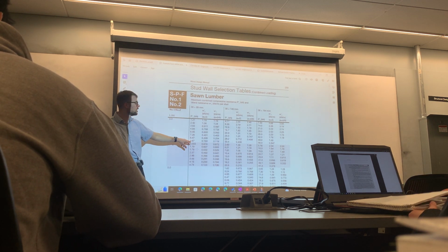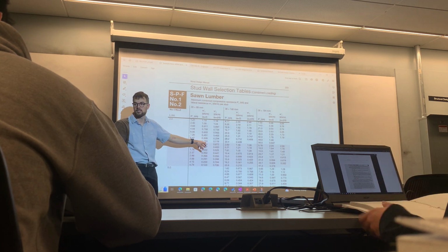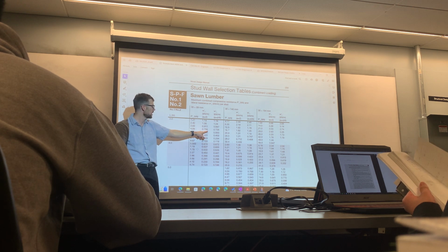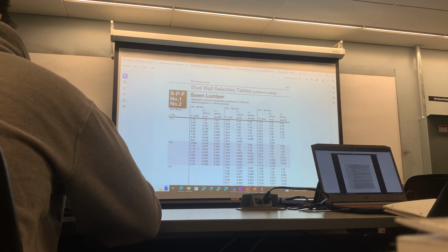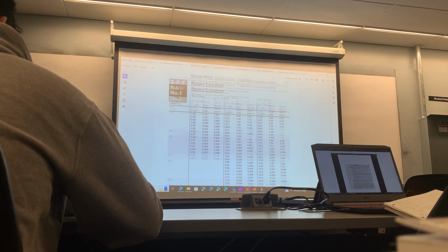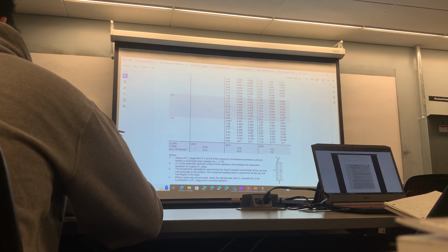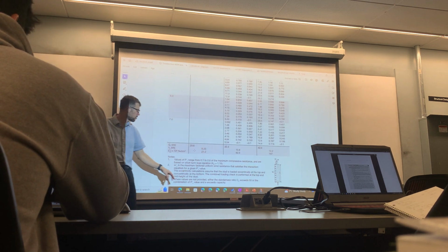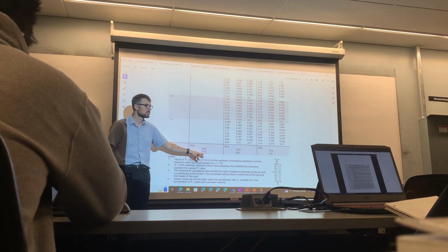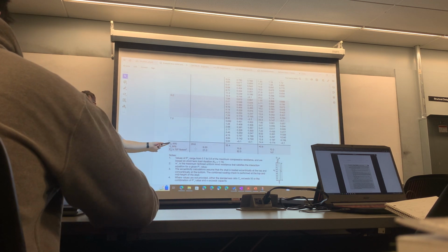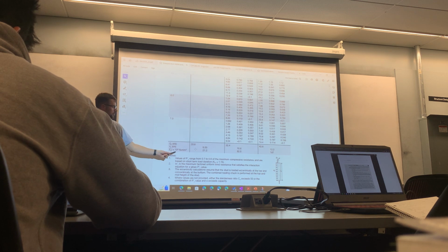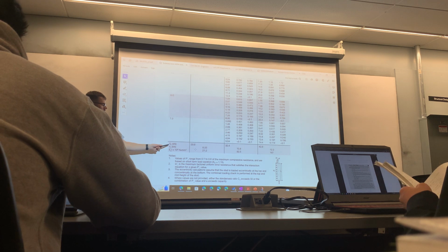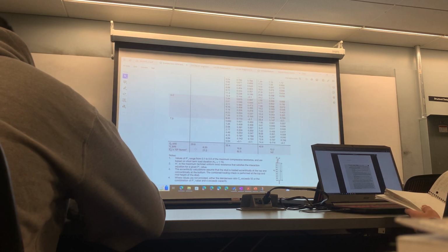What load can it support? And then with that load, is the wind load less? Sometimes you've got to go back and forth because you might find the wind load first, 0.758, and they can only support a maximum of 4.84. But we'll go through this. Then later on, we're going to check at the bottom, and you've got bearing for the stud, for crushing the plate. You've got shear, 8.33, and then you've got deflection, 21.2. You can imagine from your Module 2 calcs, we're going to be able to figure out deflection, we're going to be able to figure out shear from our free body diagram, and we're going to know compression.